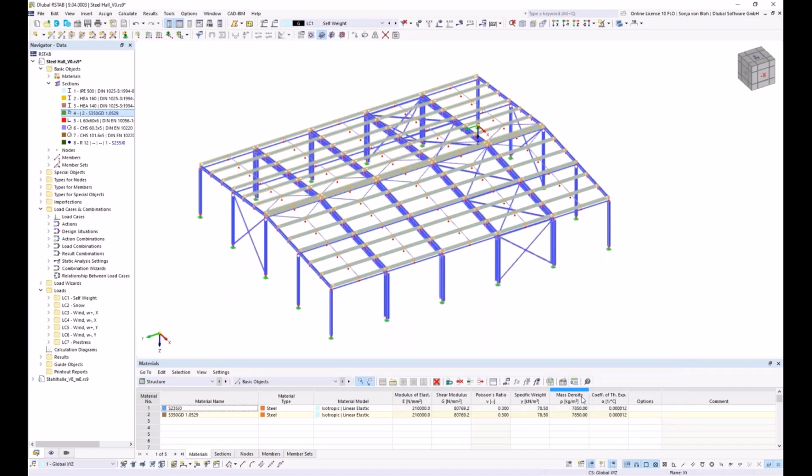For cold-formed cross sections, the center of shear lies outside the cross section and the main axes are rotated. Usually, the loads don't act on the shear center, which results in double bending and torsion. Usual lateral torsional buckling checks cannot be carried out. Eurocode 3 Part 1-3 includes design methods for cold-formed purlins, but the purlins must be within certain limits. These simplified design methods are not implemented in Steel Design.